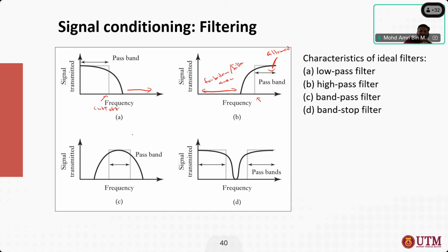And this is band pass. Band pass means that you set the low cutoff and high cutoff. So you only allow the signal in between the low cutoff and the high cutoff, or you are only interested in that range. Of course, the filtering cannot happen ideally like that. So the reduction will take some response or take some reduction.